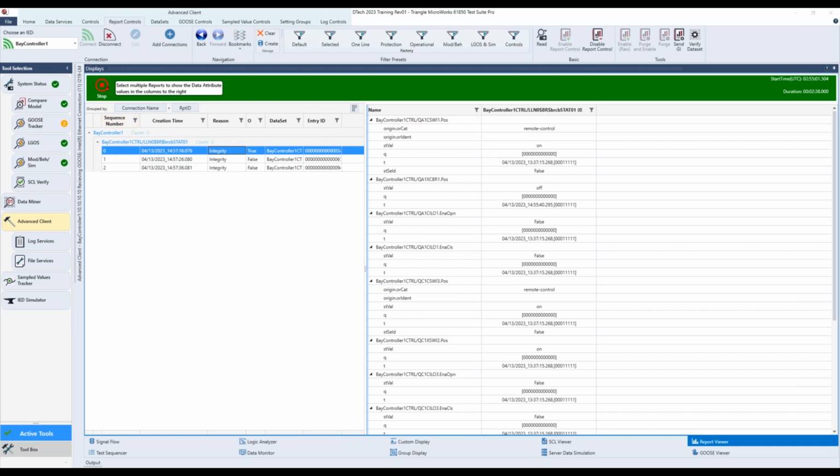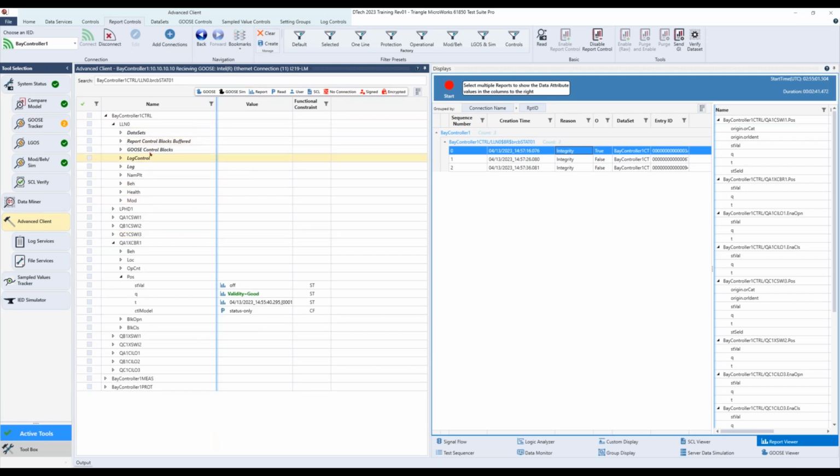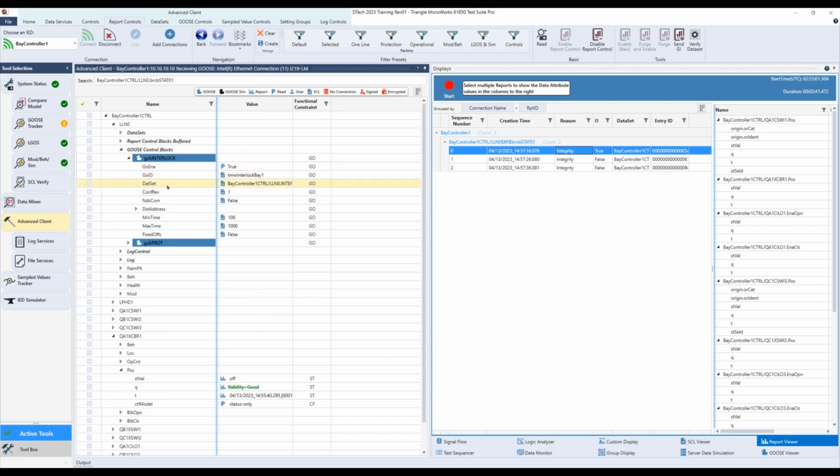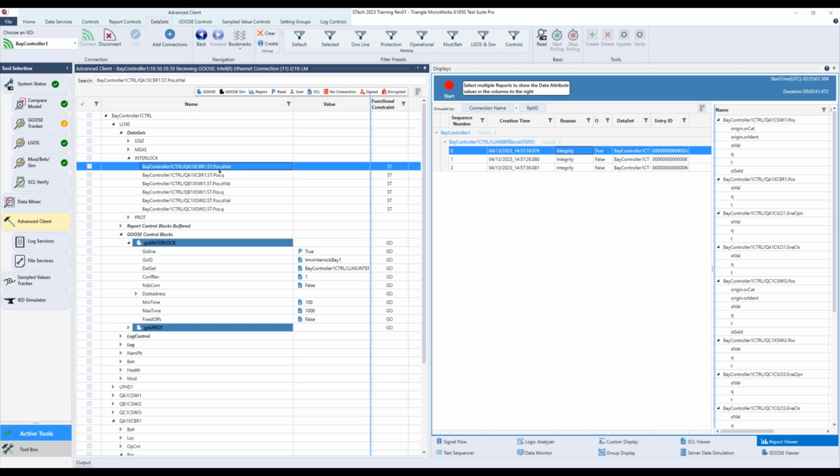And finally, before I turn it back over to Beth for Q&A, I want to take a look at GOOSE messaging. So I know we keep harping on it, but I think of 61850 as three protocols in one. The first one that we just looked at being report control blocks, and the second one being GOOSE messaging. So much like report control blocks, GOOSE messages rely on data sets, as I mentioned. And if I locate the data set for this GOOSE control block, I can see that the same breaker position value is contained in the data set. This means that if I make a change to this value and I've subscribed to this GOOSE control block, then I'll receive that message, and I'll receive it very quickly.